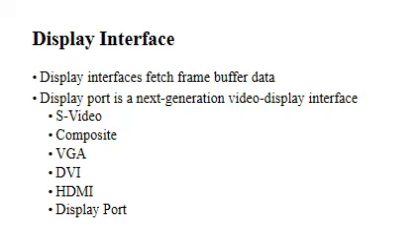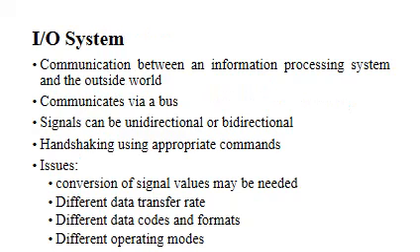However, dual mode DisplayPorts will transmit a single link DVI or HDMI signal across the interface and use a passive adapter that selects the desired signal. On the other hand, VGA and dual link DVI require active adapters and do not require dual mode DisplayPorts. Dual link DVI adapters rely on an external power.